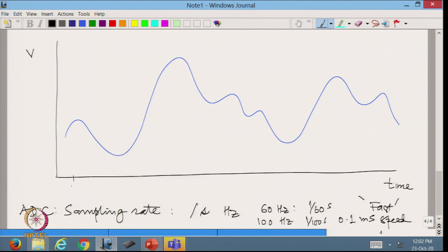This sampling rate will tell you what this time interval is. So, at regular intervals, all of which are exactly the same here, the A to D converter goes to the input and picks up data. It sees this signal, an analog value, converts it into a digital value and stores it. Then it waits, and after some time it does this again, and like that with each and every one of these points.